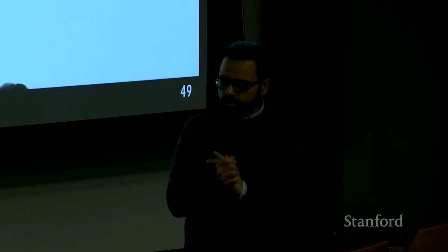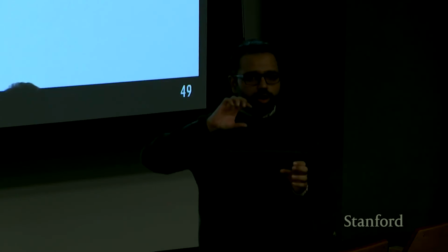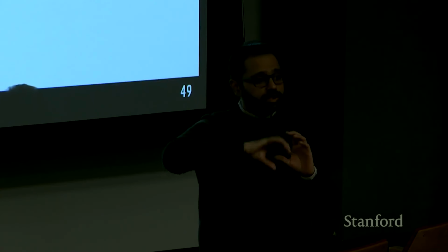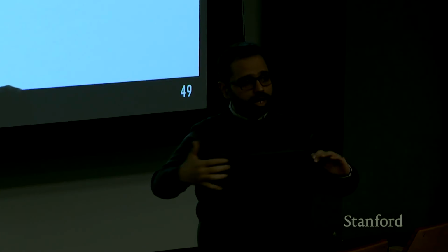What's your opinion? So graphs of convex sets, I think there are assumptions these methods are making, for example, having a convex obstacle. Or if you see how cuRobo works, they assume the robot and environment are represented with multiple spheres, and then they solve the motion planning problem very fast.